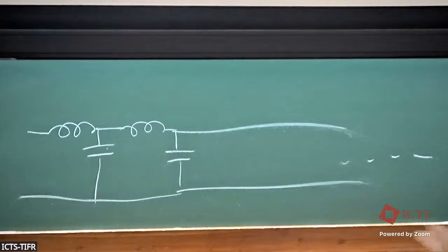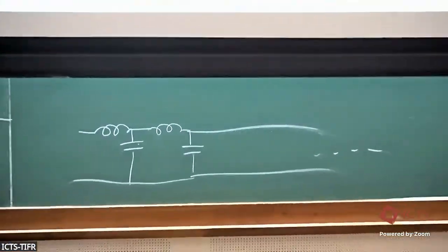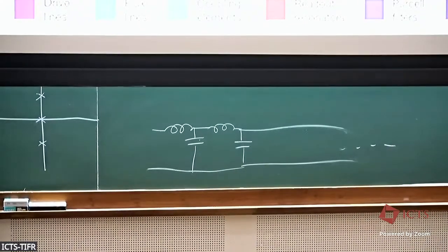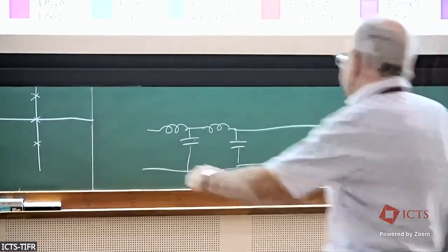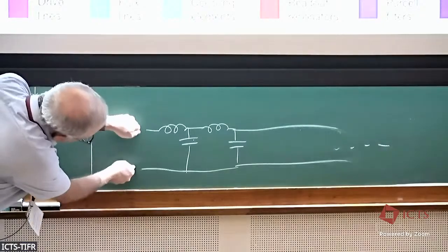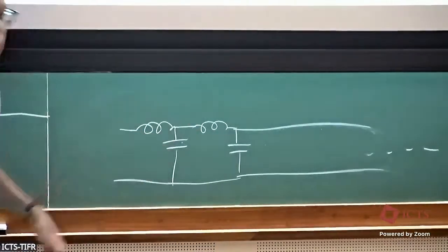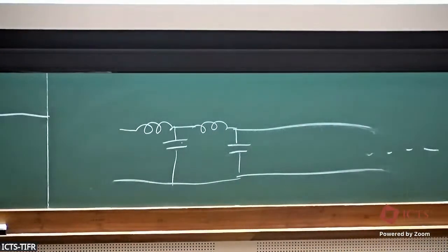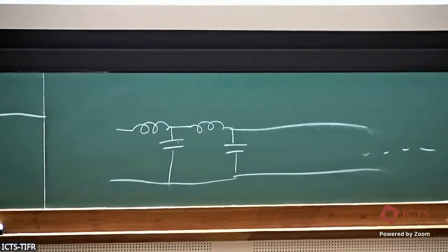These circuits have very, very few relevant degrees of freedom, so they don't act like resistors in that respect. This device has infinitely many elements, and indeed, from some point of view, if you look at it from here, and you do experiments, you can't tell the difference between it and a 50 ohm resistor. You launch energy into it, it never comes back. And indeed an unterminated infinite transmission line does actually look like a 50 ohm resistor.